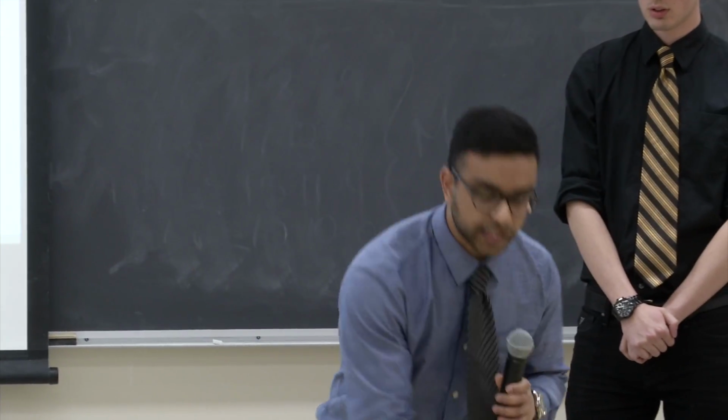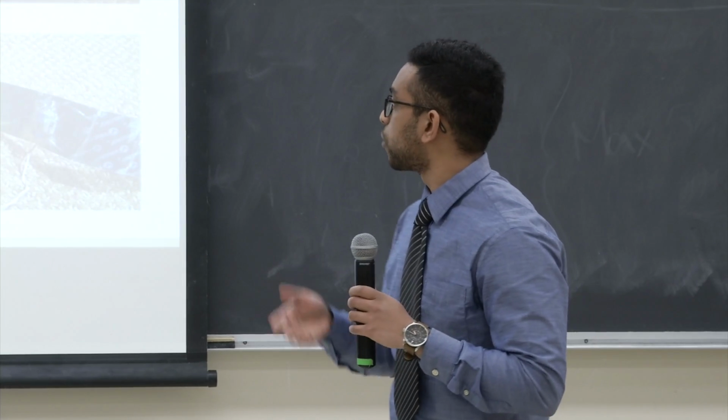So fundamentally, it all goes down to this. This is the force-sensitive resistor that we use. Essentially, it can correlate forces with changes in resistance through it. This is more of an electrical side of things and a bit more specific, but as you press down on the sensor, its resistance changes. And so through our circuitry and then through our microcontroller, the brains of the machine essentially, these can be correlated to